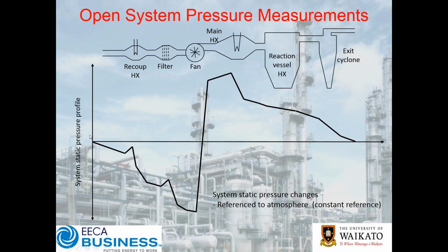You got some sort of inlet losses across some duct work. You might have some sort of recuperator or preheater. You'll notice with duct expansion you might get a little bit of pressure recovery. Then as the air is accelerated again, obviously you're then requiring more static pressure. You've then got losses across filters, intake ducts, etc. And ultimately you've got some sort of negative pressure at the intake to your fan.